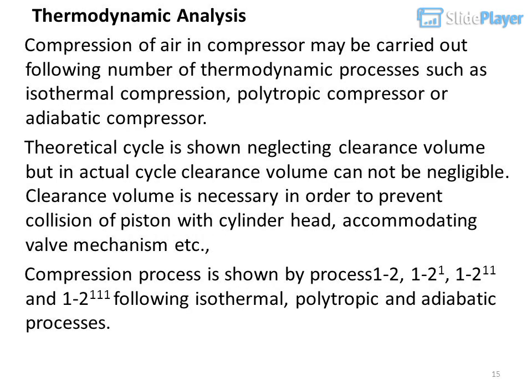Thermodynamic analysis. Compression of air in a compressor may be carried out following a number of thermodynamic processes such as isothermal compression, polytropic compression or adiabatic compression. The theoretical cycle is shown neglecting clearance volume, but in an actual cycle clearance volume cannot be negligible. Clearance volume is necessary in order to prevent collision of the piston with the cylinder head, accommodate the valve mechanism, etc. The compression process is shown by processes 1-2, 1-2', 1-2'' and 1-2''' following isothermal, polytropic and adiabatic processes.